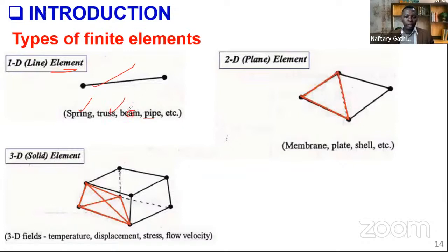The beam we extended, combining 2 beams oriented in an arbitrary plane, to get a frame. But even though the element can be oriented in a 2D or 3D Cartesian plane, the element by itself is just a line. It might have 2 nodes and degrees of freedom per node, for a beam being 2, for a bar being 1, but still a 1D line element.